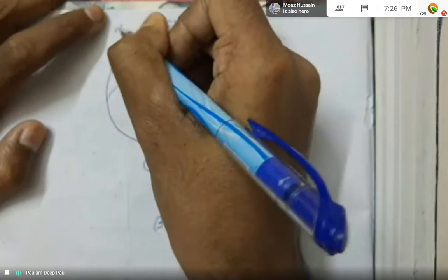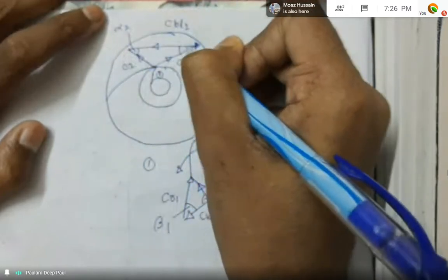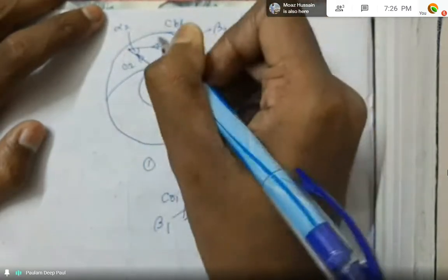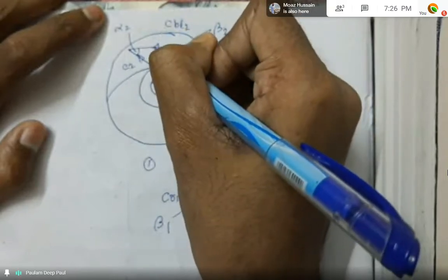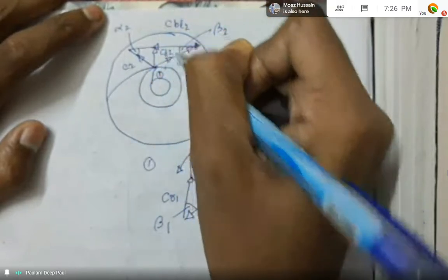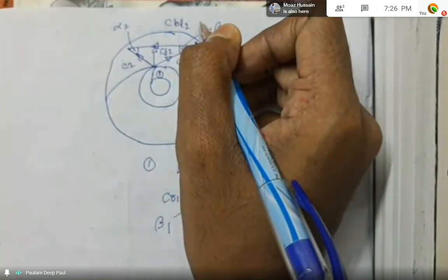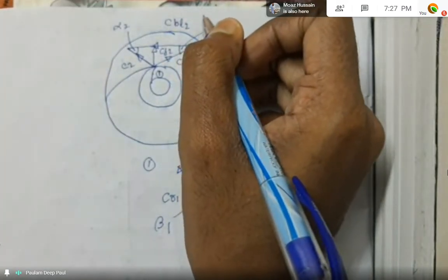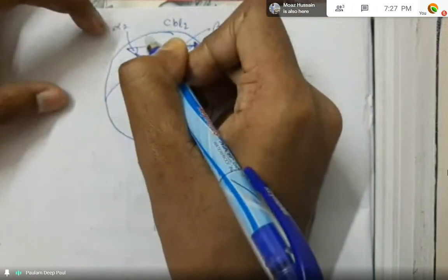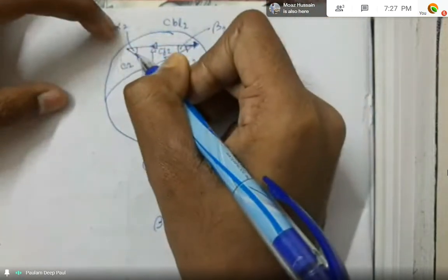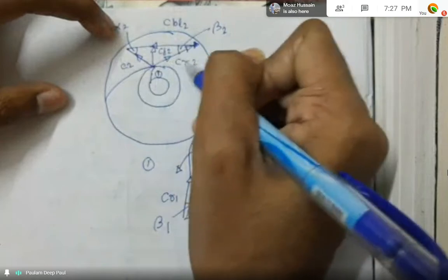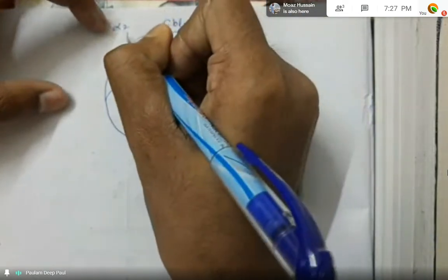Now, as usual, the outlet velocity triangle has alpha 2, and we get the beta 2, and we get a flow component, that is CF2. Now, as stated in the axial flow compressors that I told you, we get a whirl component for the absolute velocity also, and as a result of the relative velocity also.